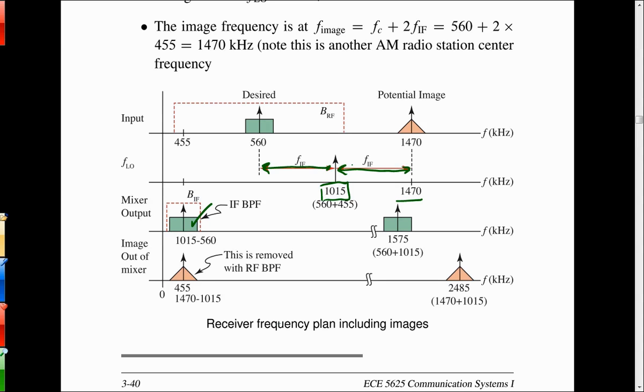But there are two carrier frequencies that you could demodulate at the 560 kilohertz, get it to 455 kilohertz, right? Yeah, it would be the sum, which is what's up there, the 1015. And if it was the difference, then wouldn't the image have to be on the low side, but you run out of spectrum because then it becomes negative. It doesn't really become negative because if it's a real signal, it's symmetrical. So the spectrum will have its mirror, and that's what you'll be working off of then.